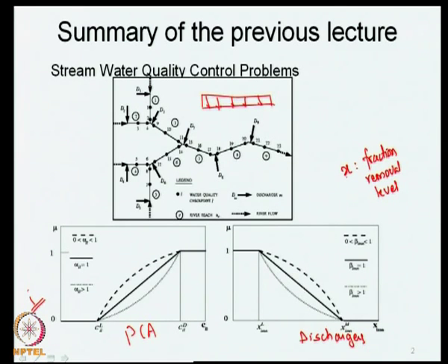So, we are relating the treatment to be given at discharger M for the pollutant N to enhance the water quality index value I. So, that is why we indicate this as XIMN. I is the water quality indicator, M is the particular discharger, so in this particular case D1, D2, D3 etc., DM, and N is the particular pollutant. Remember, the type of pollutants that we are talking about in this example are non-reactive pollutants.